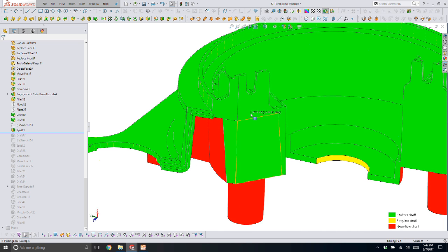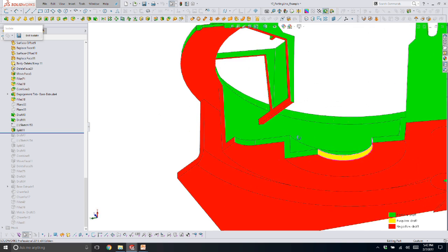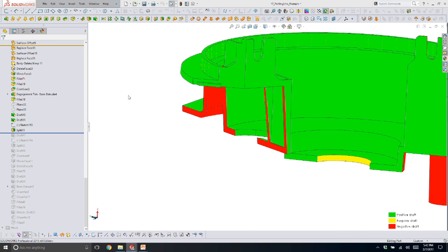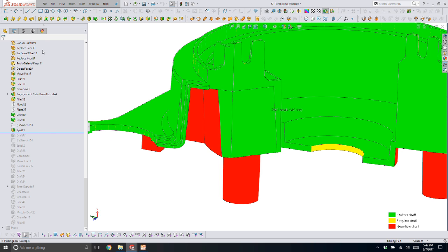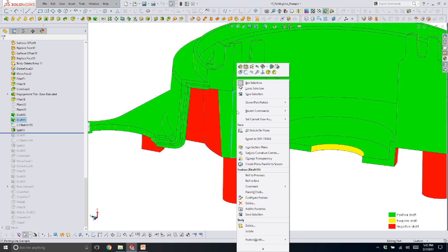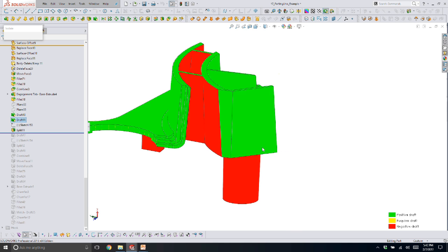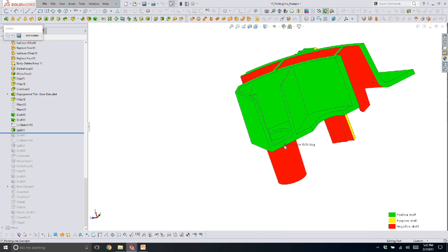And so what I've actually done is, if I were to isolate this, I've cut the part in 2 pieces. And if I just use the split line, you said, well, why didn't you use a split line there to add the draft, and then split line, and then add the draft to these faces? It wouldn't build. I need this one extra face, and I get the shutoff face for free. So now, when I isolate this body, I have a new face in my model right here.